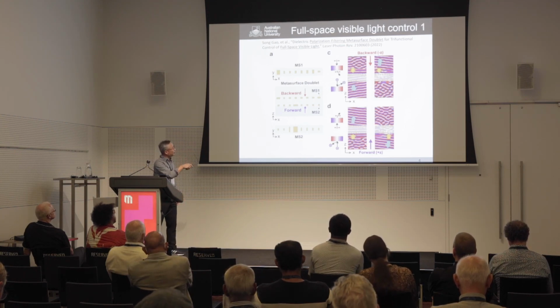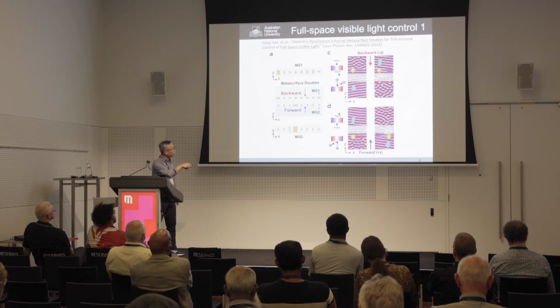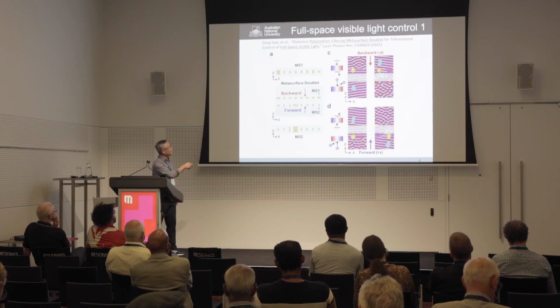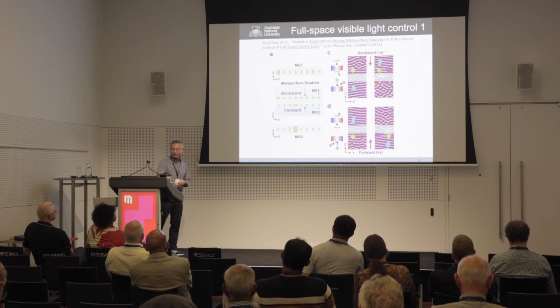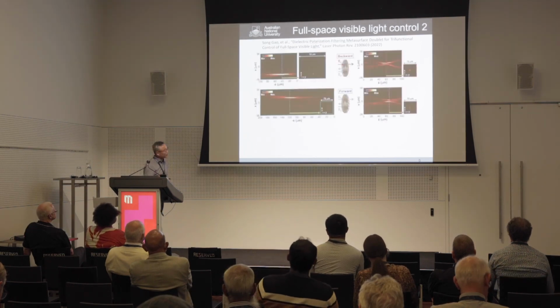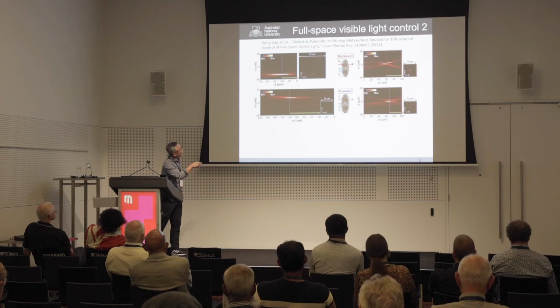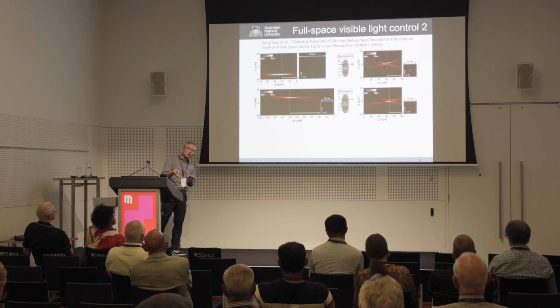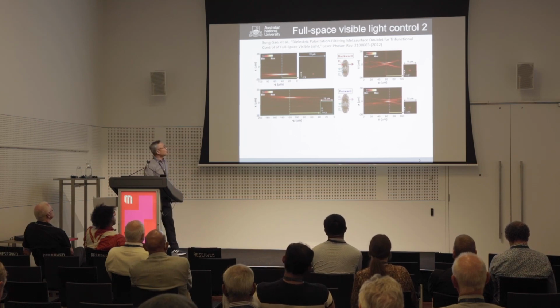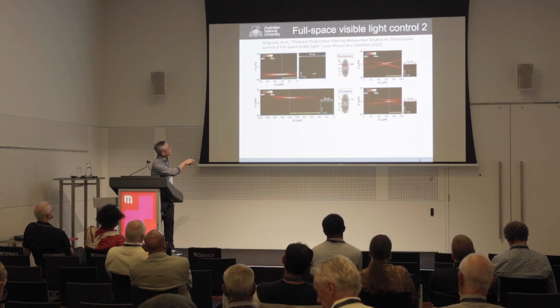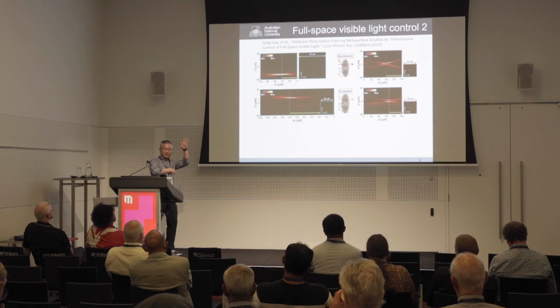So it can transmit in TE mode, in forward direction and backward direction, but it can reflect in TM mode. MS1 can reflect doing one function, and from this side, MS2 functions another way. In the experiment, TE goes through and makes some complex vortex beam generation, going forward or going backward, it's the same. But for the reflection mode, TM mode, it reflects and makes some deflected light at a little bit different angle.